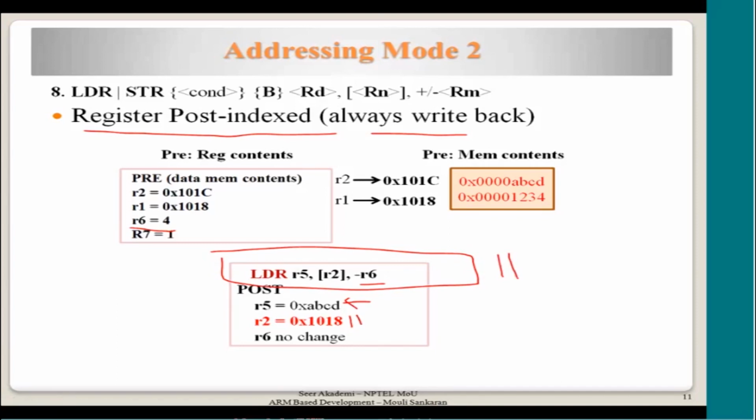Like what I did, initialize this with the num1 and the LDR instructions that I showed you in the beginning. Use them to load these values with the proper addresses, and initialize this memory with these values with a .word and then 1 2 3 4. I am writing 1 2 3 4 so that every nibble is different. That's why I have chosen this value so that I can show you some examples.